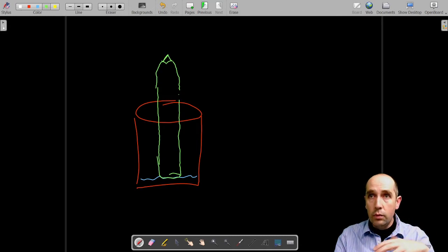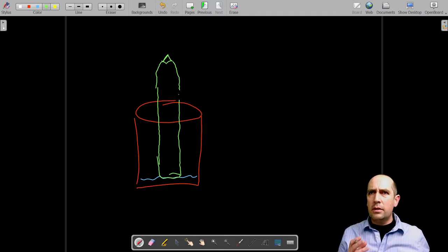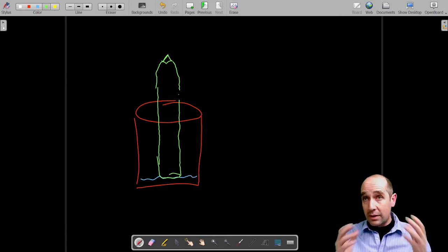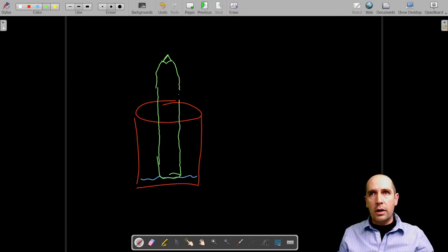So when you melt the silicon, you can add a controlled amount of group 3 or group 5 materials in order to make the material p-type or n-type, and not just p-type or n-type, but really control how many carriers per cubic centimeter one introduces into the ingot.